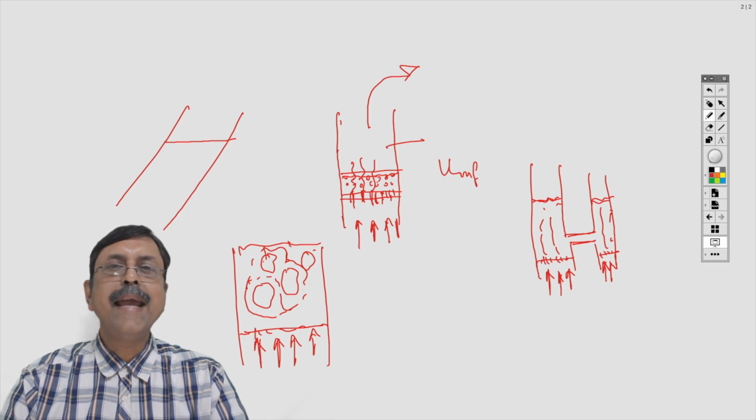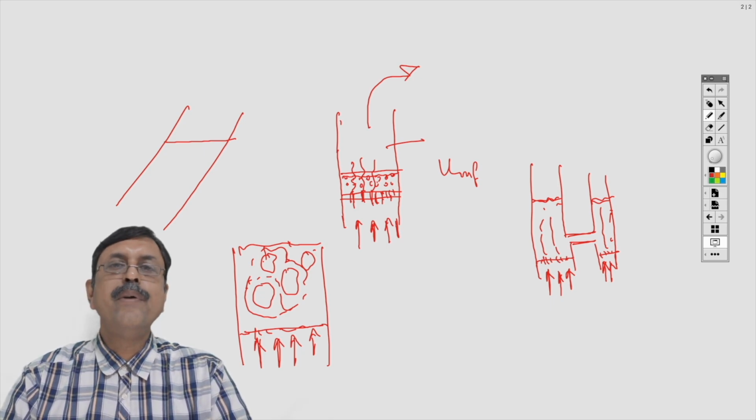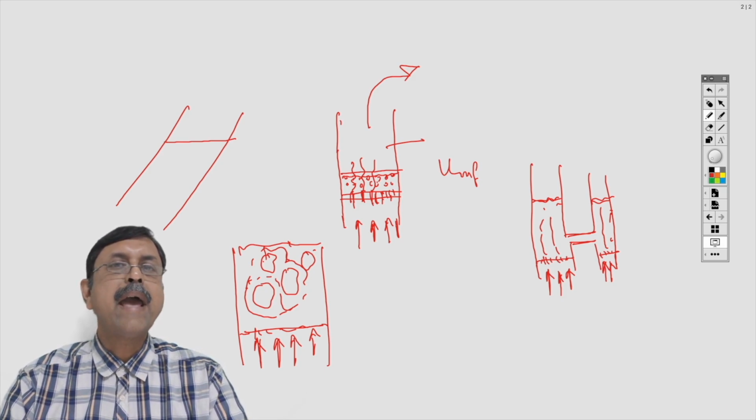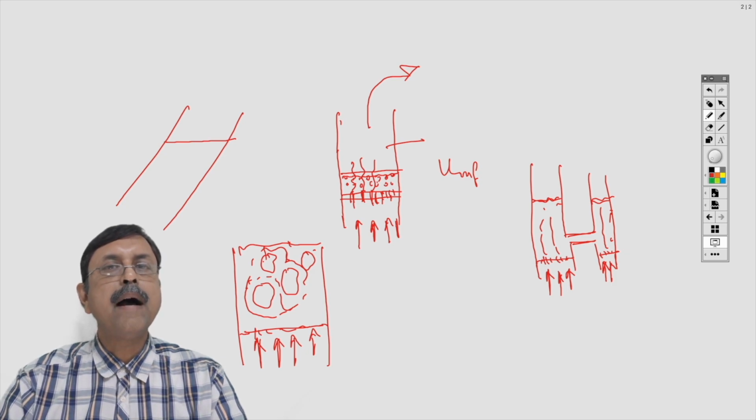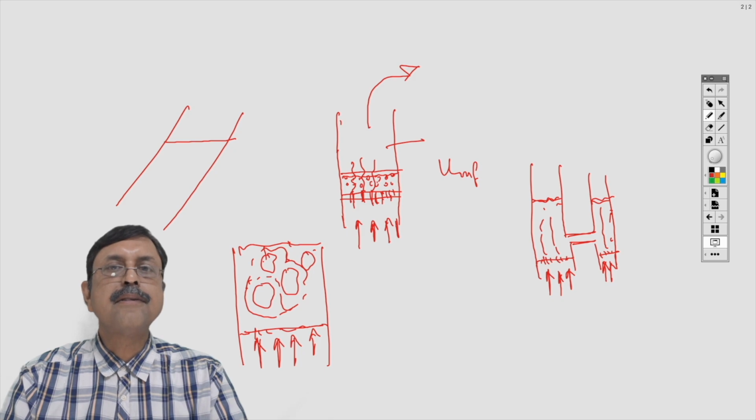Because for any chemical engineering operation which grossly depends upon the surface area of solid particles, this kind of fluidized bed will be very useful. For instance, drying. If you have to dry solid particles, then fluidization is very effective. You can pass hot gas, fluidize the bed, and it will dry very fast.